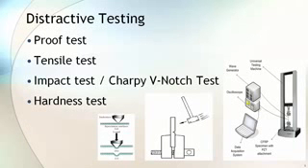Destructive testing is performed to check the strength of the body and weld of the product. Proof test is also known as type test or burst test. Manufacturers use this test to qualify the fitting design. Fittings are welded with pipe and pressurized up to the burst pressure calculated by design or till the fitting bursts. This is a one-time test to qualify the fitting design.